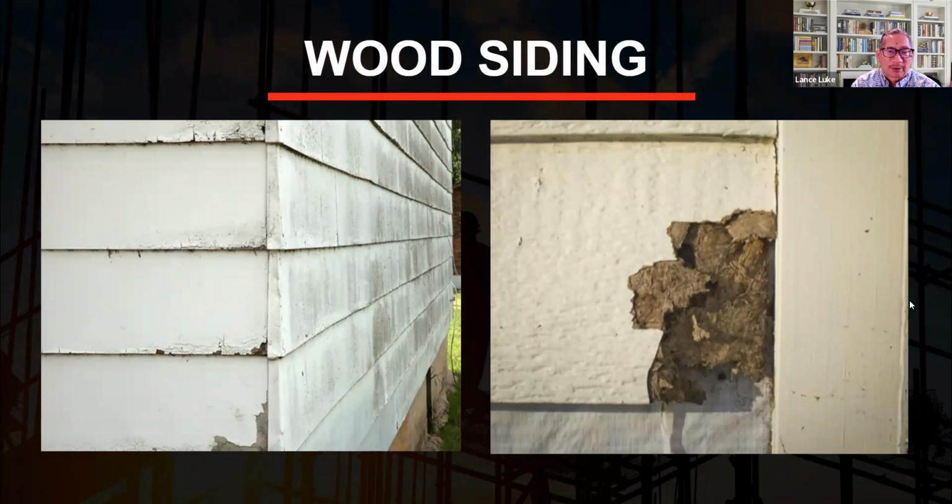And in the beginning, all the manufacturers got sued in a class action lawsuit because it was determined that all their siding failed when exposed to the weather, such as sun, wind, rain, mostly rain. When it got wet, it acted like cardboard, and it soaked up the water, and it expanded and started cracking. So if you see that, there are buildings up today that still have this siding. It's just been painted over or spot repaired.